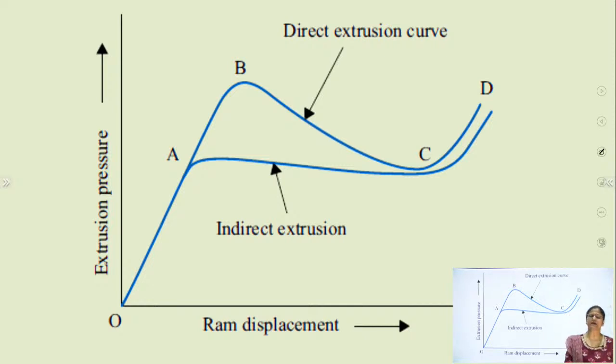So it is generally recommended that when the extrusion process is at the end and only the thin disc is remaining in the cylinder, it should be removed from the container, because it is uneconomical to force the thin disc through the die hole.